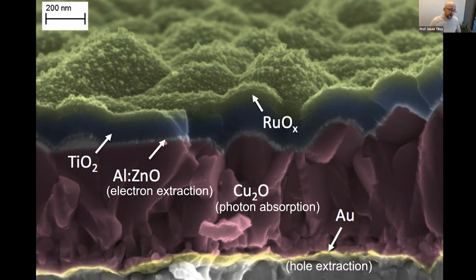So the zinc oxide is also not very stable in water. So we put this TiO2 as a passivation layer. And I should point out, we do this by deposition, by a method called atomic layer deposition. So we can basically grow very thin layers, with atomic layer control of different materials. In this case, we use about 20 nanometers of zinc oxide and about 100 nanometers of TiO2. And basically this minimizes the chance that we have a pinhole.